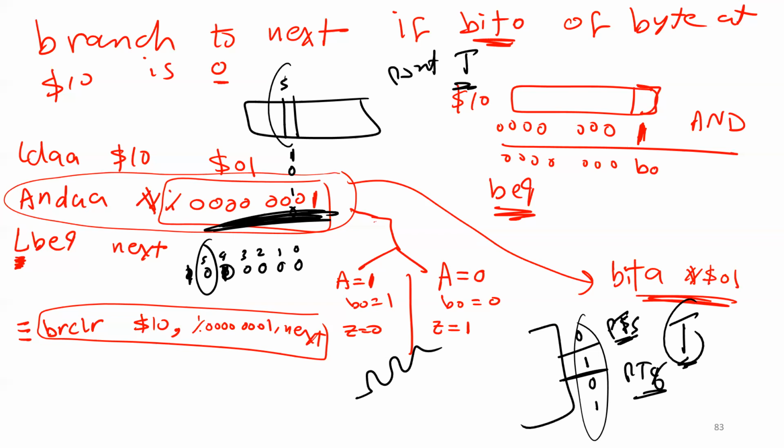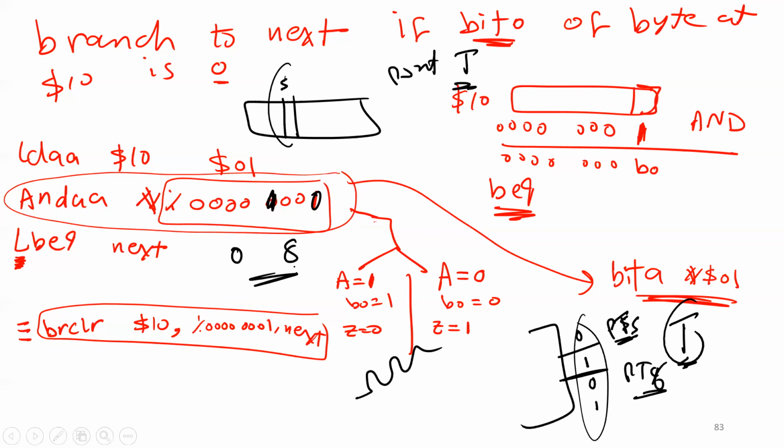So what I'm saying is, if you want to do it in binary, because it may be easier for you, because for example, you already know you want to put a 1 in this bit or in this bit. For example, here the 1 is here, so this should be 0x08, right? 0, 8. Again, either way is okay, hexadecimal or binary. However, if you want to do binary, make sure you put the 1 in the correct location. I'm not sure if I answered your question.